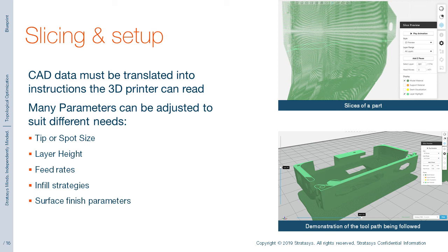No 3D printer works directly from CAD data. They all employ some type of CAD-CAM process that translates this 3D data into a series of 2D slices or toolpath instructions. And this is actually a good thing. Whilst you could just take some default parameters and print seemingly directly from a 3D CAD file, taking an interest in your slicing and printer setup will always give you a higher quality result.